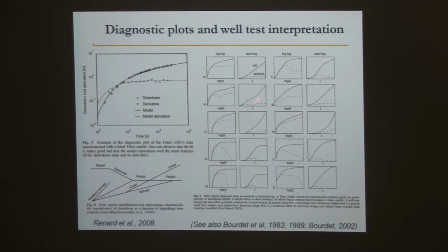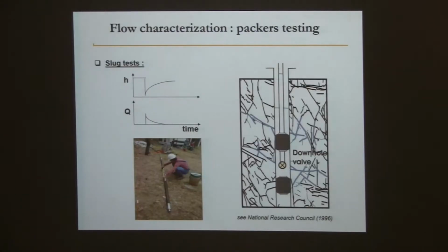In fractured rock, for instance, what is often used, even if we can discuss that, is typically the double porosity medium, where the matrix porosity has some permeability. Typically this approach allows you in some cases, if the permeability is sufficient, to somehow characterize the boundary condition and the overall permeability.